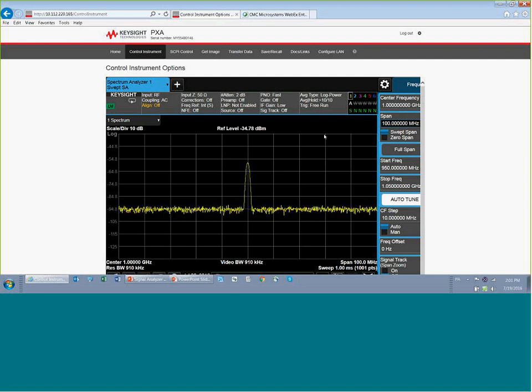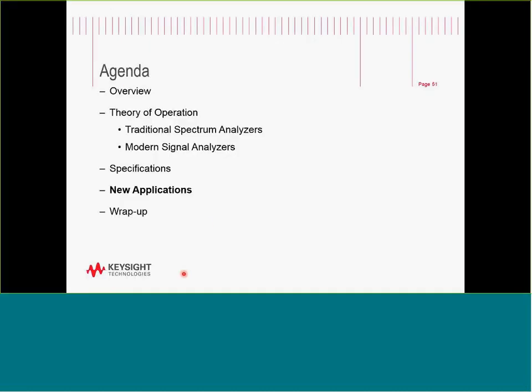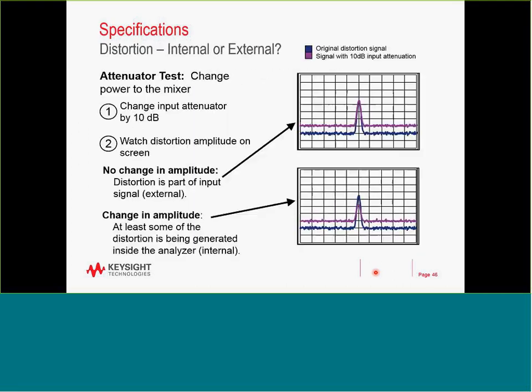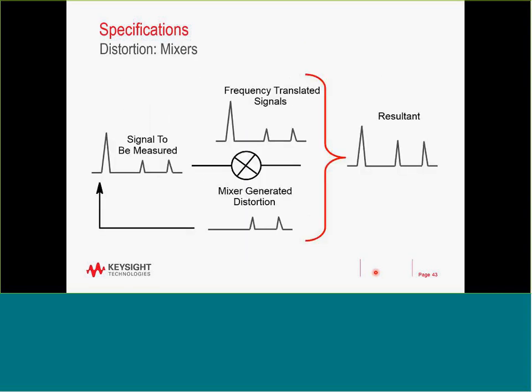Oh, and then just a couple of questions regarding some basics. This is a great presentation, in my opinion, for demonstrating the considerations a researcher has to take into account when setting up their signal or spectrum analyzer to make measurements. Now, if one was measuring the output of a mixer, how are the harmonic components from the mixer, say alias components that might be coming down from the sampling, handled? Is that taken care of with the input filtering?